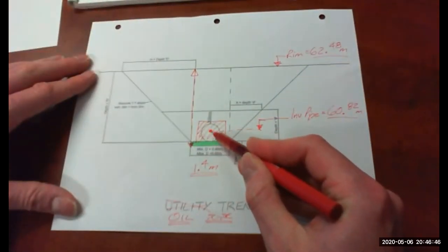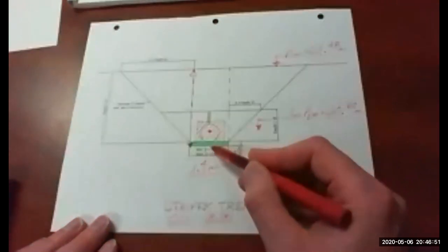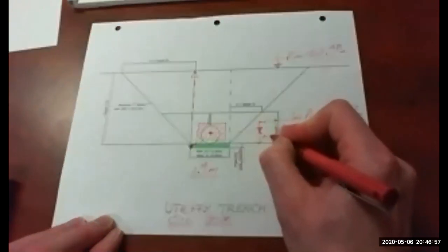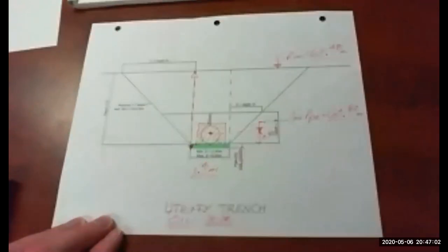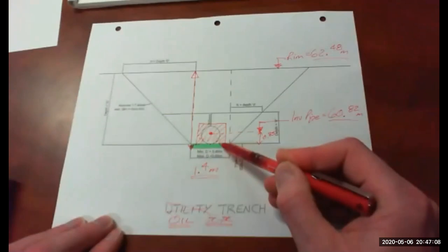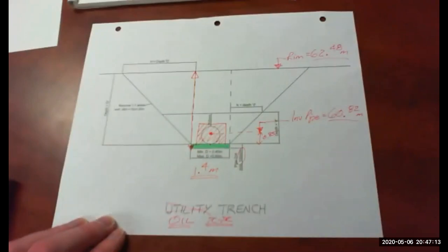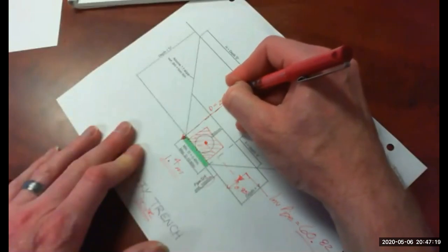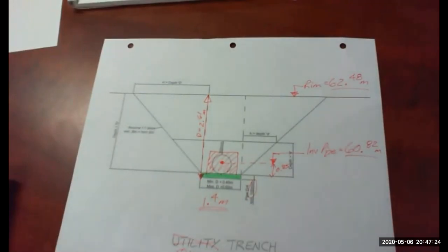We add in the 0.85 that the question tells us, the information that we're told. So this here is 0.85. So I need to add that. And then lastly, we need to add the 100 millimeter thickness of bedding. So I'll add 0.1. That gives us a depth of 2.61 meters to the bottom of the bedding.